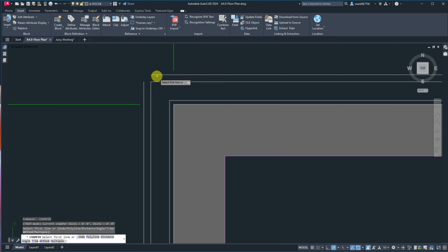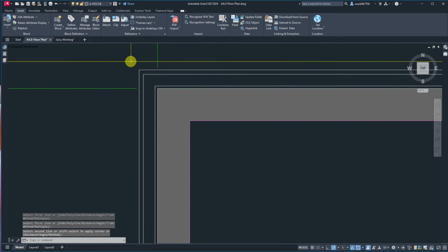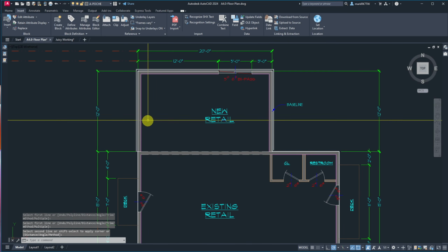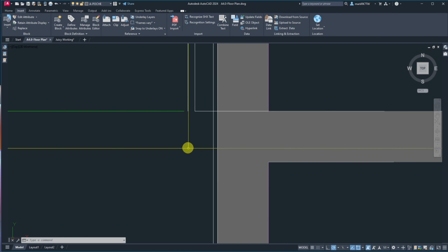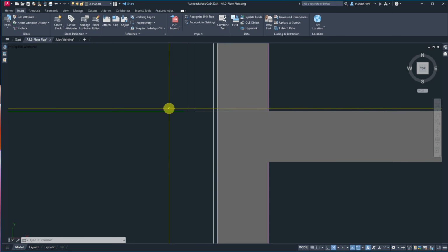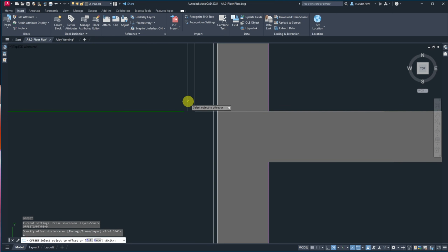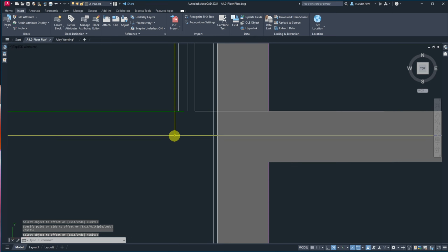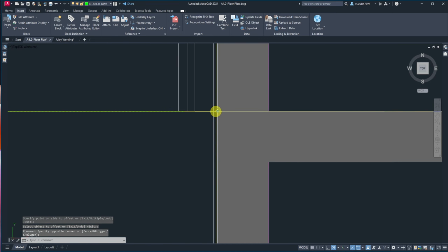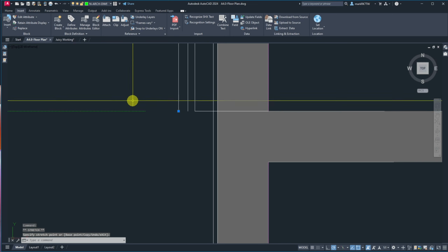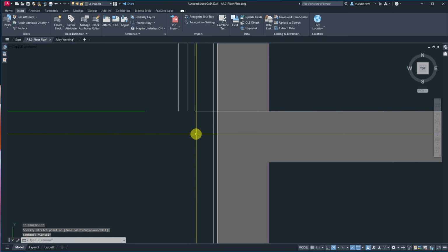This is such a small project I could, but this is just the convention that I use. So this will be chamfered out too, but now I'm going to add offset 1 inch. They want Hardie plank, and by the time you get that stuff lapped, it turns out to be pretty darn close to 1 inch. I'll take my dimension, drag it out so I get a nice clean line break there,